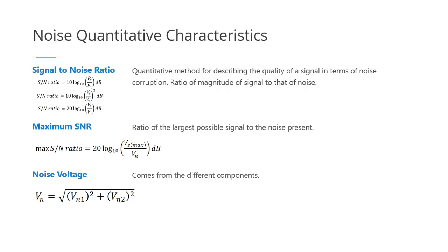So the effect of noise is technically not about the noise power alone, but how it compares to the original signal power. If we have a large signal power and a relatively small noise power, then it would not be as big of an effect. So instead of the noise power being the sole quantitative measurement used to quantify noise effect, it's actually the signal to noise ratio.